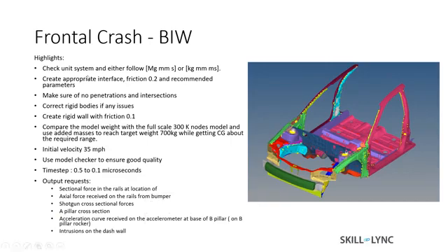First of all, to start the model, you need to check the unit system, either Megagram, that is tons, mm and second, or kilo, mm and millisecond, based on how we have discussed in our classes until now. I would recommend this particular unit setting, but in the output or in the project report, you have to give me results along with their units. Whichever unit system you follow, I'm okay with it. It's just that you have to mention your own units when you give me the results.